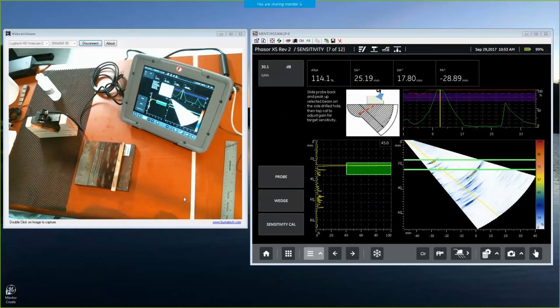What we'll do, we'll do what everyone else did. So if you're sweeping, say 30 to 70, which would be a big range, you go 30 to 45, and then it does 45 to 60, and then it does 60 to 70 in different sections. So it's effectively a blocking gate. The problem is if you have any variation when you go section to section, you get a very crisp line along that angle that ultimately doesn't hurt your inspection. It just makes the picture look a little worse. But that's really the only way around that.